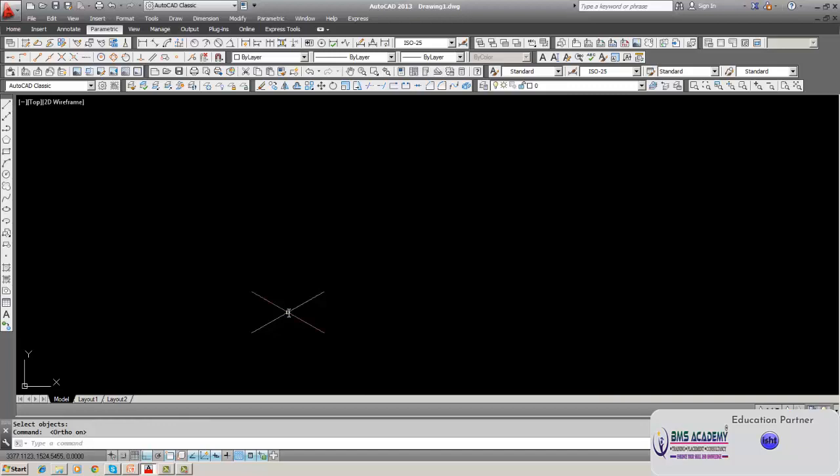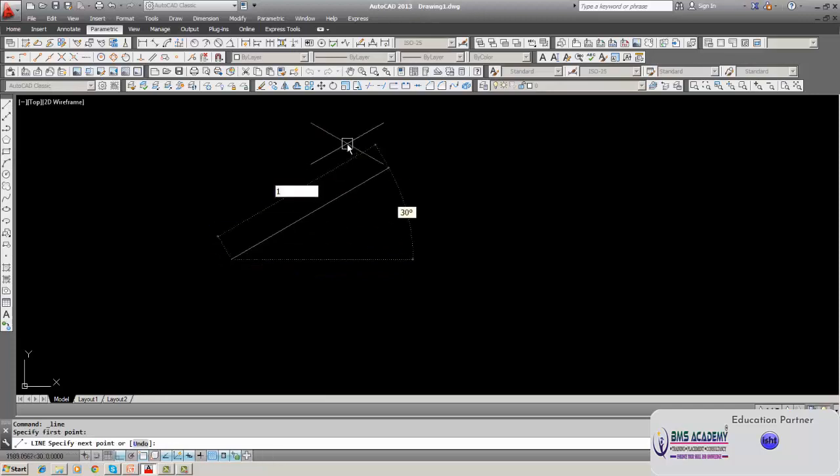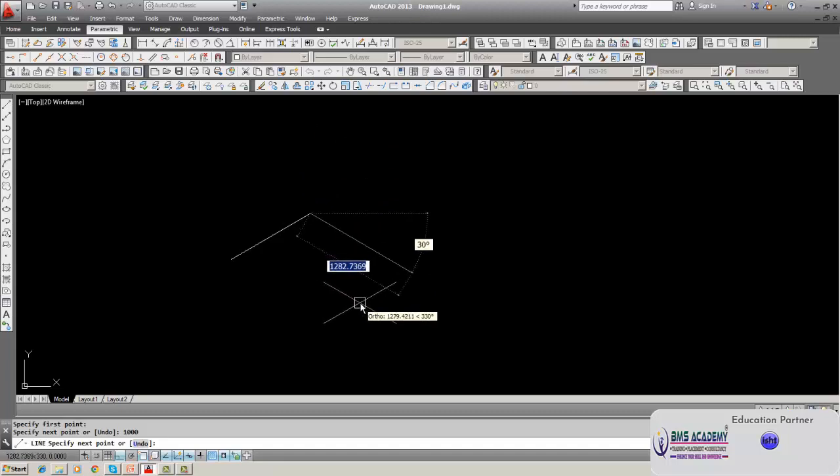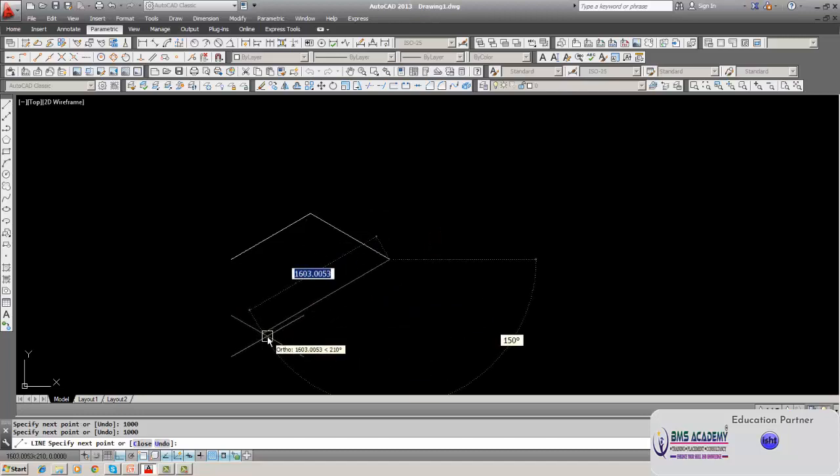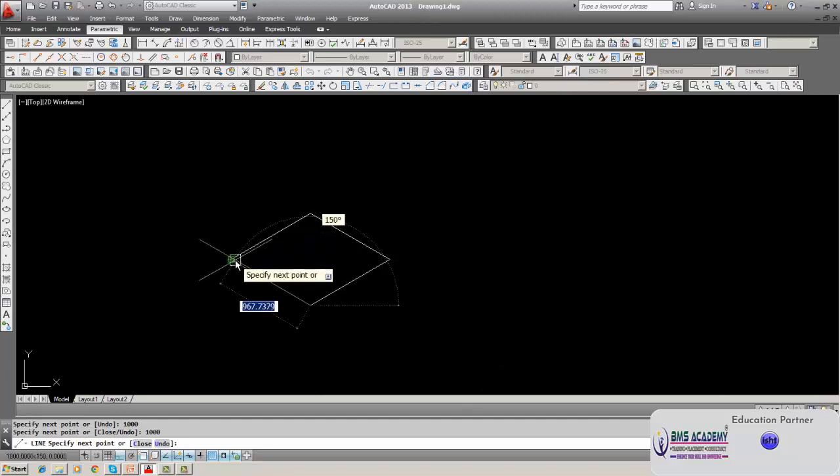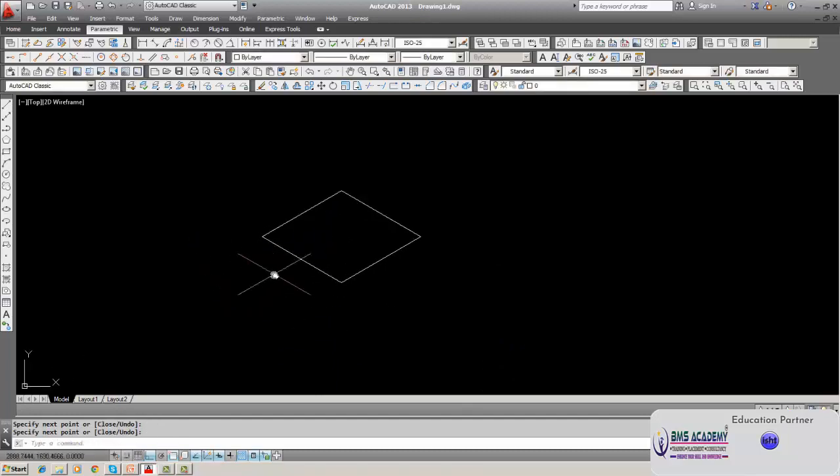Polar tracking mode should be selected in a different situation where you want to draw internal parts. But here, to draw the regular isometric line or boundary, you had better select ortho mode. This is ortho mode. Then the movement of the cursor will be proper. So here you click. We will say 1000, and then here 1000, and here also you can say 1000, and then you can join. So now we got it correct because the movement will be ortho.